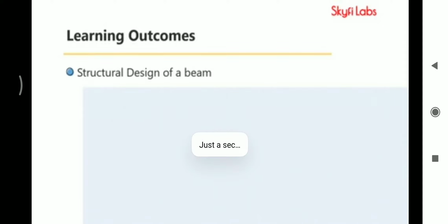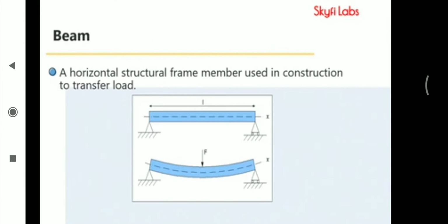In this video, you will learn about the concepts and considerations in structural design of a beam, which include spans, supports, and loading. A beam is a structural element that primarily resists loads applied laterally to its axis. Its mode of deflection is primarily by bending. In a framed structured building, it is used to transfer loads from slabs to columns.